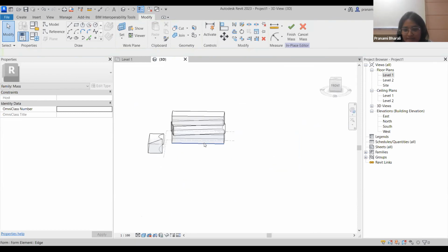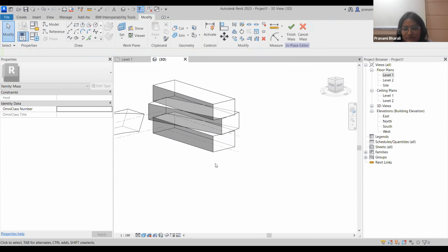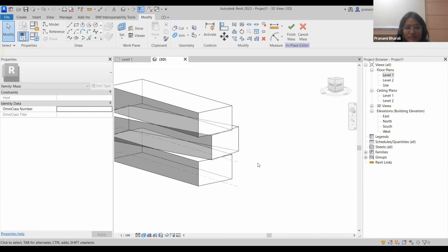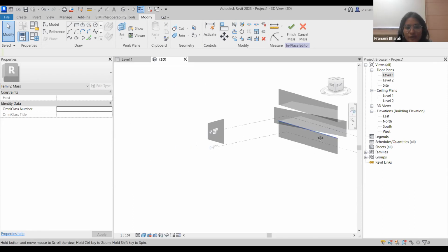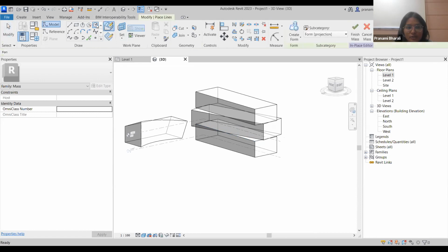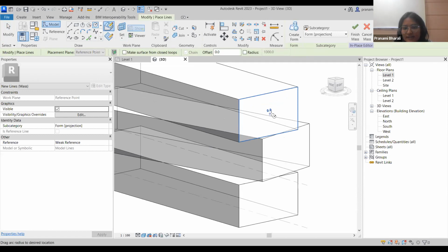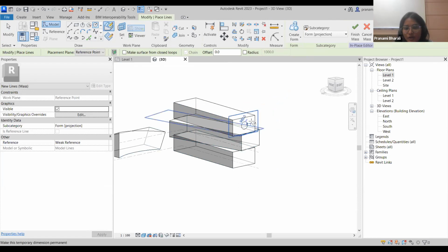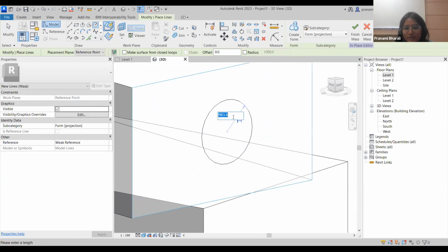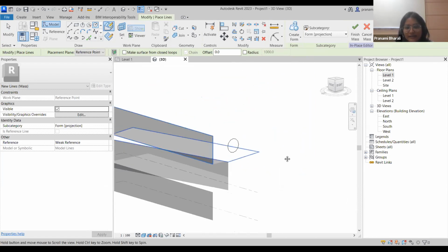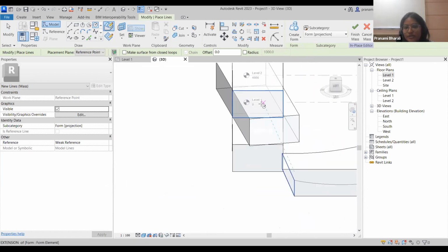So this is how the massing environment, as you can see, is very flexible, right? If you want to create any kind of void also in here, that is also possible, right? So if you want to create a void, suppose maybe you can go for the circular option in here, and this time you have to use the face option, right? So this face is getting highlighted, as you can see. So in here also you can make the circle, maybe you can give the appropriate dimensions and everything in here, right? And in this exact same side also you can try making a void here, right?